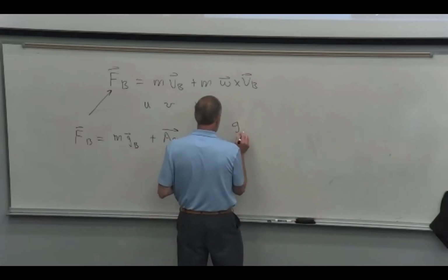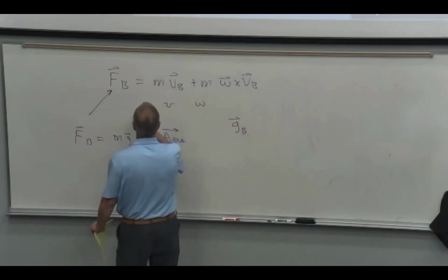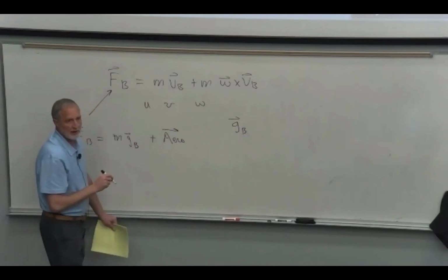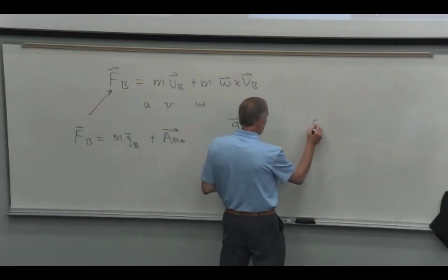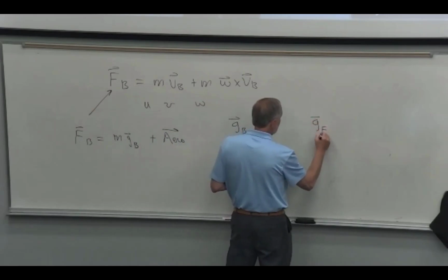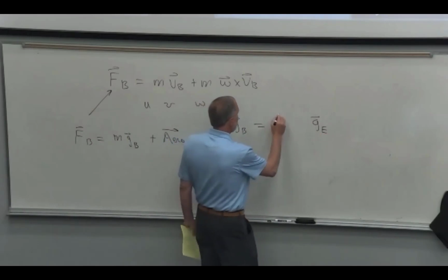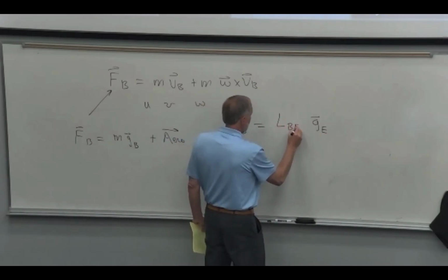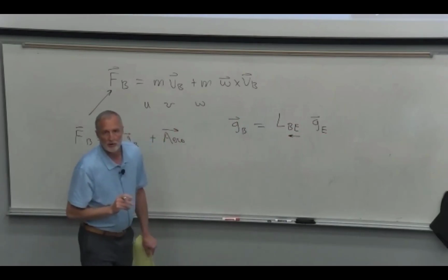The first thing we're going to work on is the gravity vector, and we need it in the body fixed axis because this equation is in the body fixed axis system. So we know the gravity vector in the Earth fixed system, it's in the Z direction down. So we have to transform it from Earth to body using the Euler angle transformation.